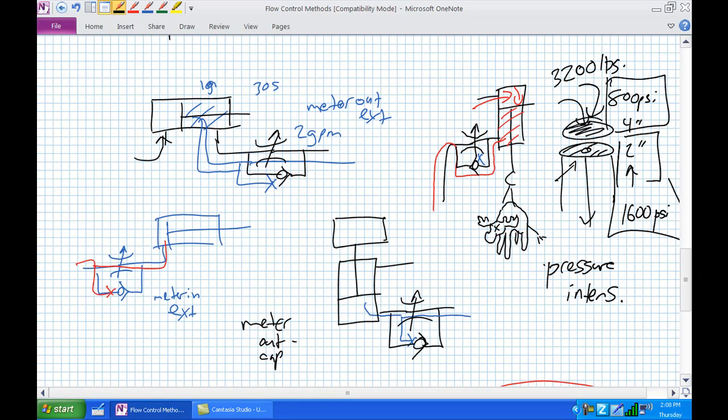So just be aware that hey, my system's 800 psi, and these hoses are good for 1,200 psi, so I'm good to go. Yeah, you might not be because of pressure intensification. And now go ahead and add an additional, let's say, how big's a moose? I don't know. A lot of pounds. Just add more force pulling down there.